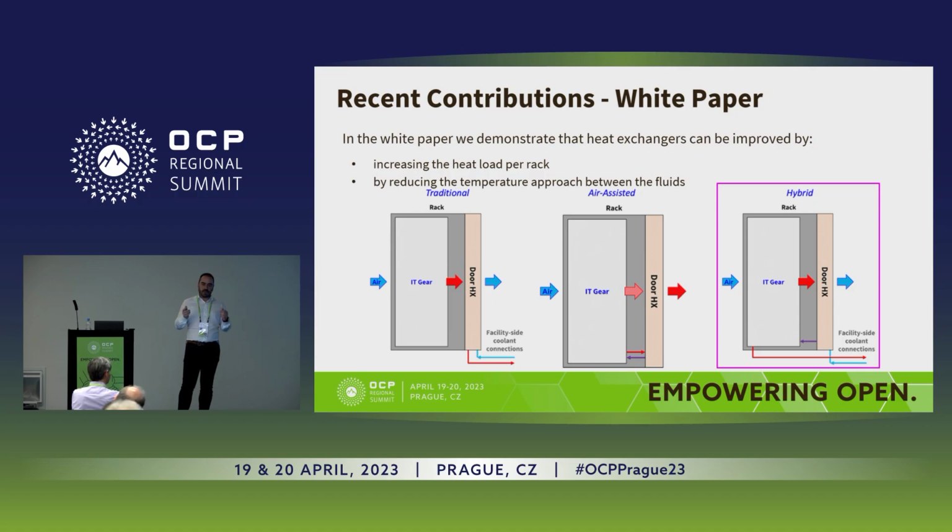So in that case, there is a possibility to use cold plates to avoid this problem. Increasing the water temperature from the facility water will reduce the energy consumption of the chillers and free cooling system and so on, but maybe increase the power consumption of the fans of the server. We have to consider this point. And the solution for this part could be to use cold plates.